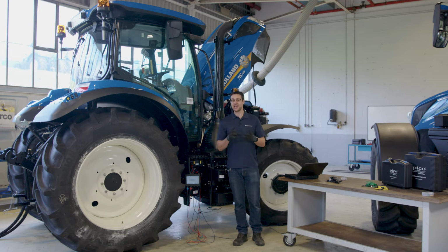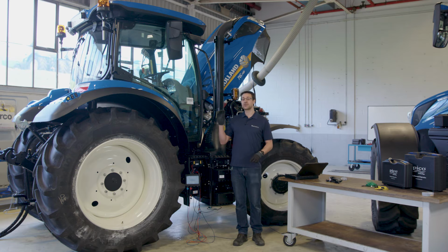I can't stress how important the source address is when it comes to fault finding. It may be that there are several gateways between your serial tool and the network that you are looking at. So how do you determine whether or not there's a problem with the network or a potential problem with the gateway? Well, this is where Pico can be really helpful, because by decoding that J1939 network, getting those source addresses, we can see which ECUs are online and which ones are not online.